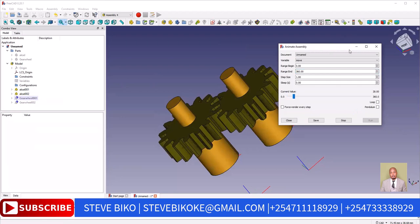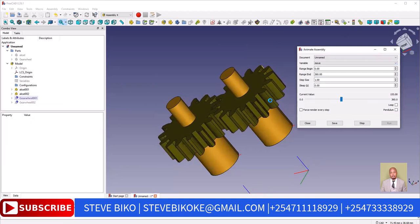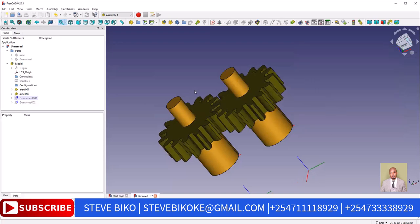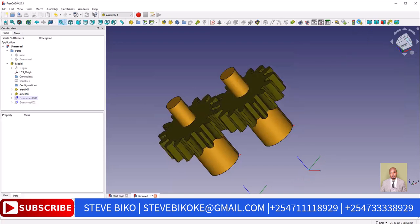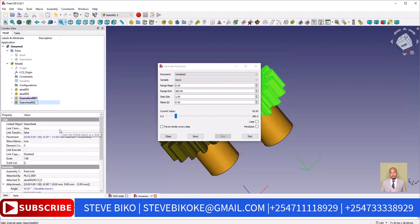And now you can see our gear wheels. And you realize that our gear wheels are running in the opposite direction. So we need to adjust that. So what we will do, we press stop. We click one of the gear wheels. So I choose the lower gear wheel.